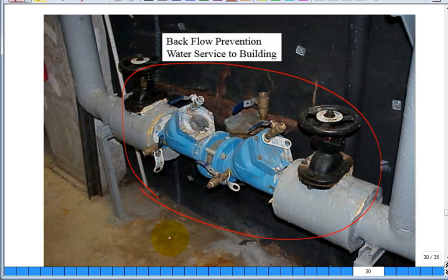City Public Service, no, SAWS, that's right, they supply water. So San Antonio Water System, when they give you a gallon of water, they never want it back out of your building because they don't know what you did to that gallon of water when it was in your building. And I'm so glad that they're not taking back into the distribution system stuff that's been in different people's homes or buildings, because who knows what's going on with that water. So these are all over the place, these backflow prevention devices. I didn't think I'd have time to really go into the detail, but they're like a check valve. That's what they are.